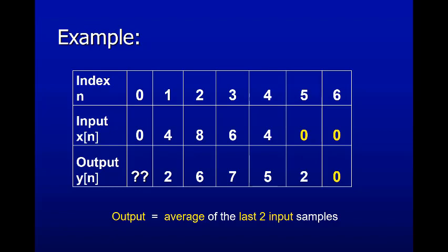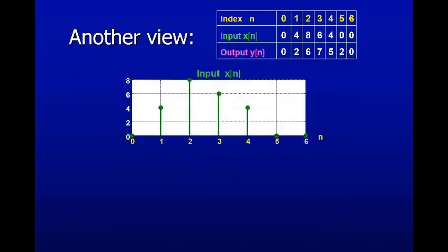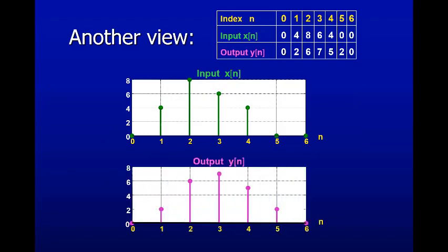We'll move to the unit sample response. That'll be our standard input, and that will give rise to the method of convolution for how we can do system analysis. If we choose this very carefully, we can take the response of the system to that particular input and then generalize it to find the output for any signal.